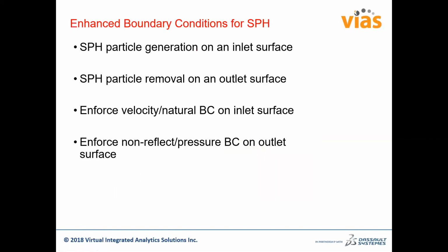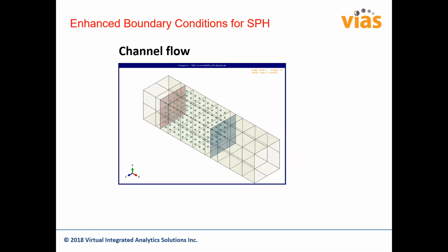Right. In SPH, we have this new enhancement, which is again very useful. I remember in the past, I have seen people struggling with this kind of analysis when they wanted to model water or something being forced into a structure. Then we actually had to model a bulk of SPH elements at the inlet and pressurize it to enter through an orifice. But now with this enhancement, you don't need to do that.